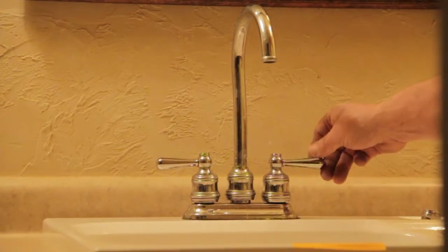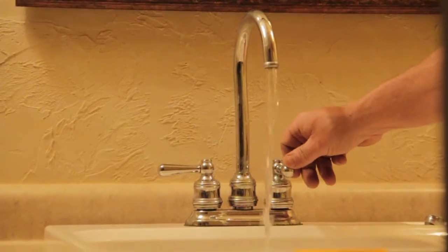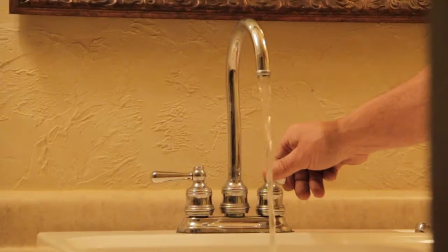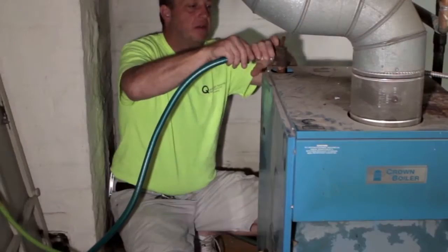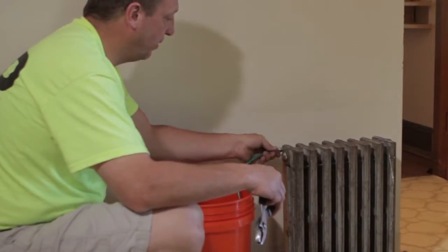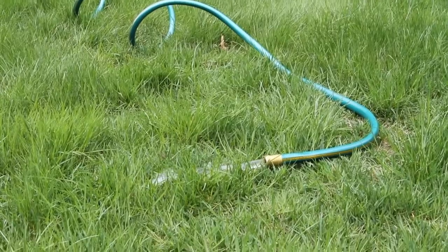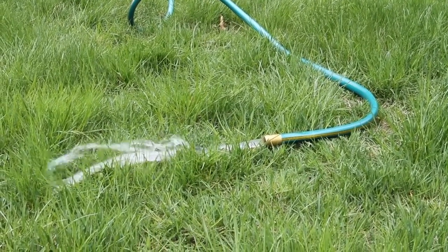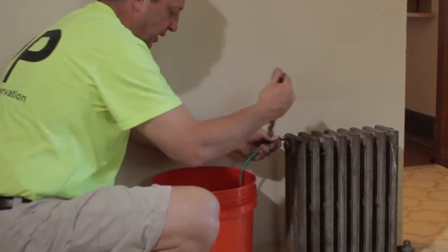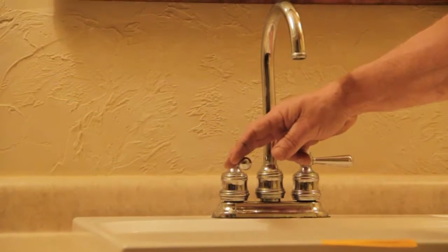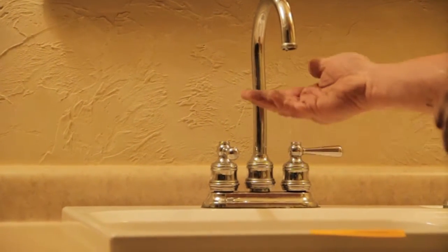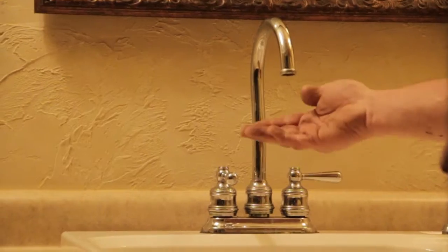After the appropriate water valves and breakers are shut off, you will start a gravity drain by opening all faucets and valves and by draining the boiler, expansion tank, and all radiators with a hose into a floor drain or outside away from the foundation. Once the gravity drain is complete, close all faucets and valves. In this step, it is important that all faucets and valves are opened, drained, and then closed.